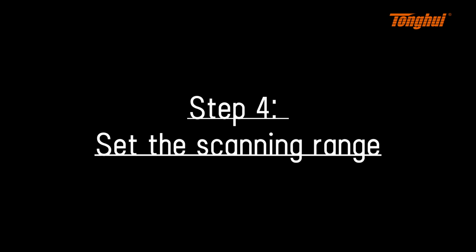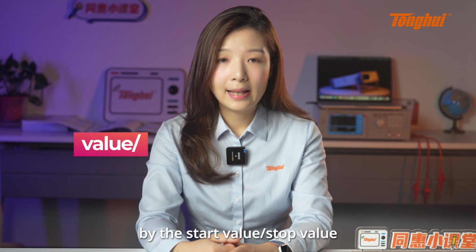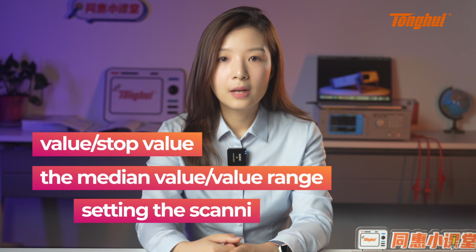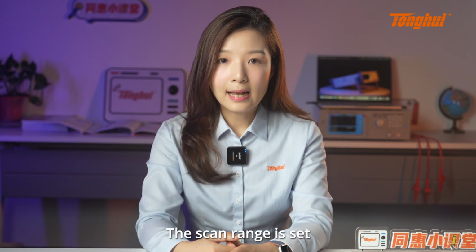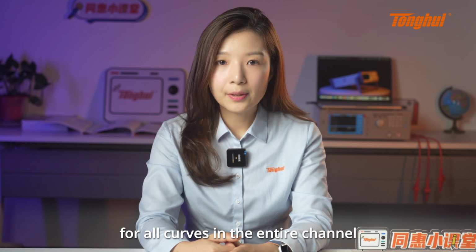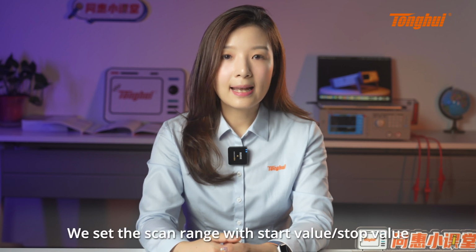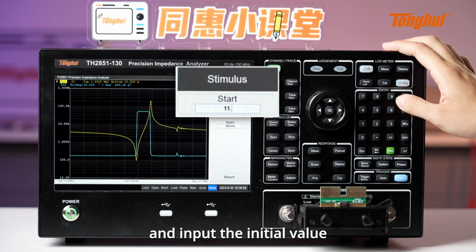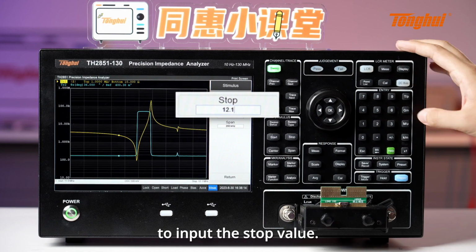Step 4. Set the scanning range. The scanning range can be set by start value and stop value, and can also be set by median value and value range, or by setting the scanning range with the cursor. The scan range is set for all curves in the entire channel, so there is no need to switch the active curve. We set the scan range with start and stop value. Press Start on the front panel to enter the Scan Range menu and input the initial value. Press Stop on the front panel to input the stop value.